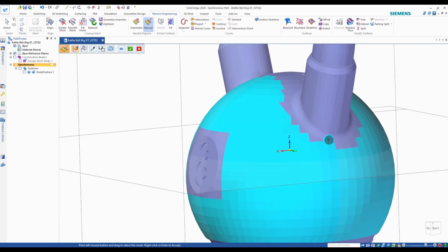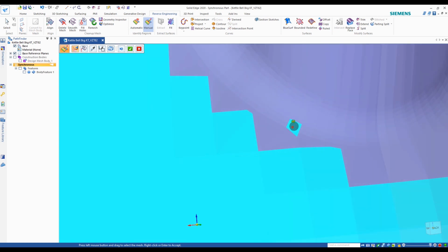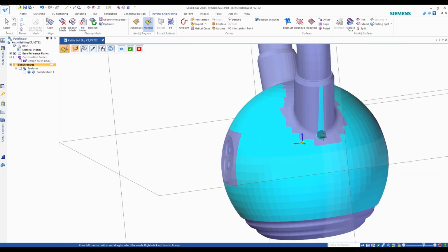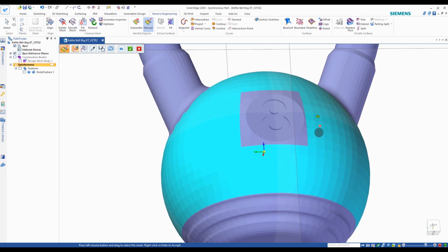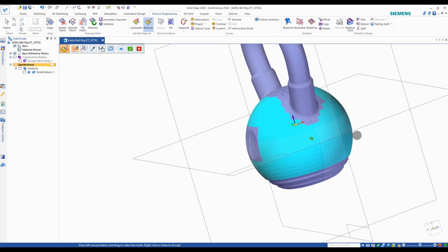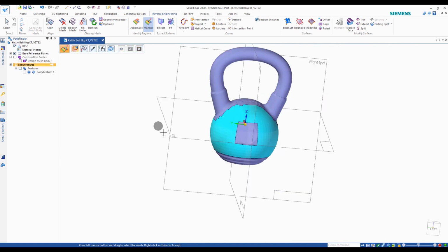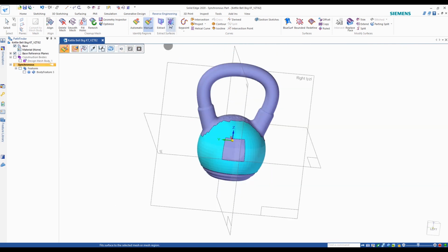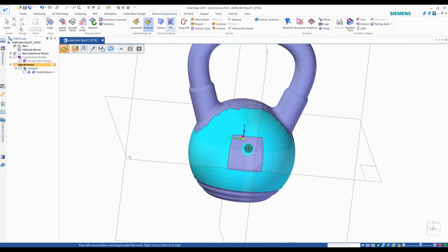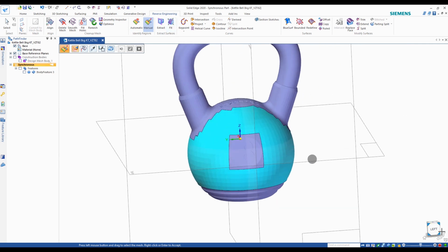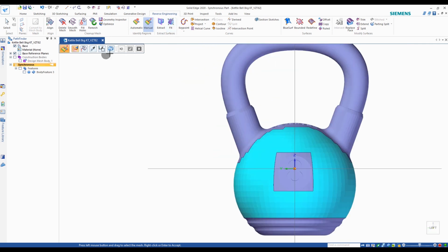So as I mentioned, you want to avoid these rounded areas. You don't want it to reflect your surface when you're trying to capture that as a sphere. So we'll click the check mark to accept that, and now you see you have this filled in region here that you can use the fit command afterwards, and we'll fit a sphere using that as a boundary.